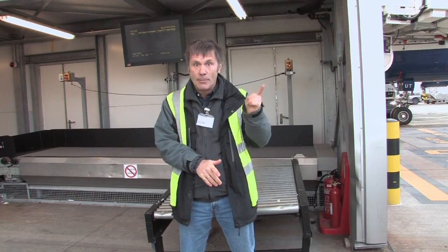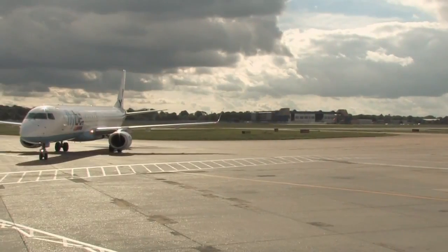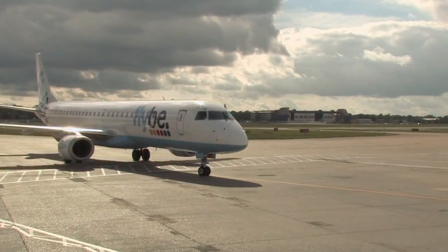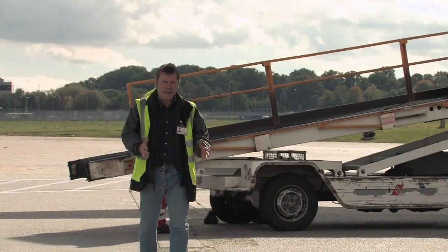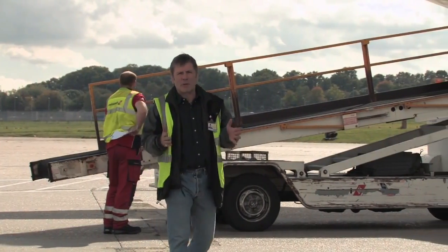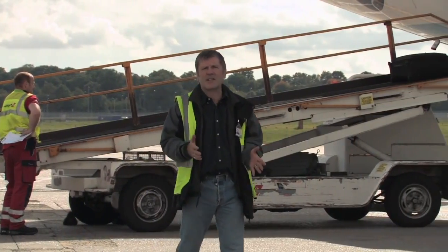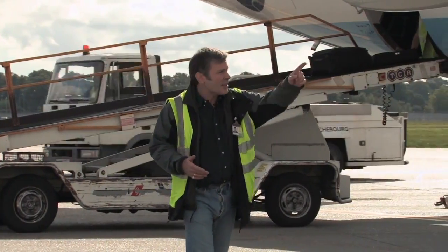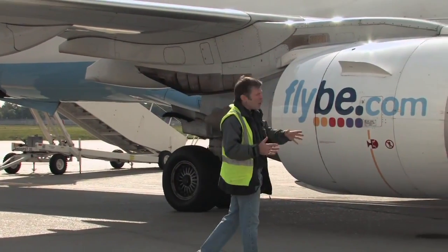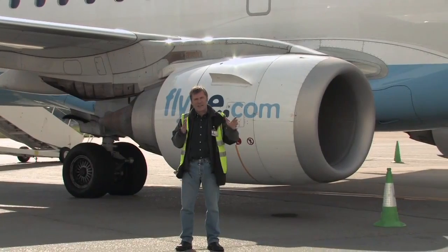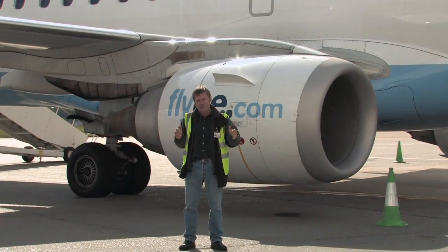Now then, I'm now officially a piece of self-loading freight. I am now going to become part of the weight and balance of an aeroplane. This aeroplane. Typically, there are three main areas where you can distribute load on an aircraft. Doesn't matter whether it's a passenger aircraft or a cargo aircraft. There's the whole of the upper deck. There's a cargo area behind the wing and there's another one forward of the wing. Anywhere you put load in any of these locations will affect the centre of gravity and the trim of the aircraft.